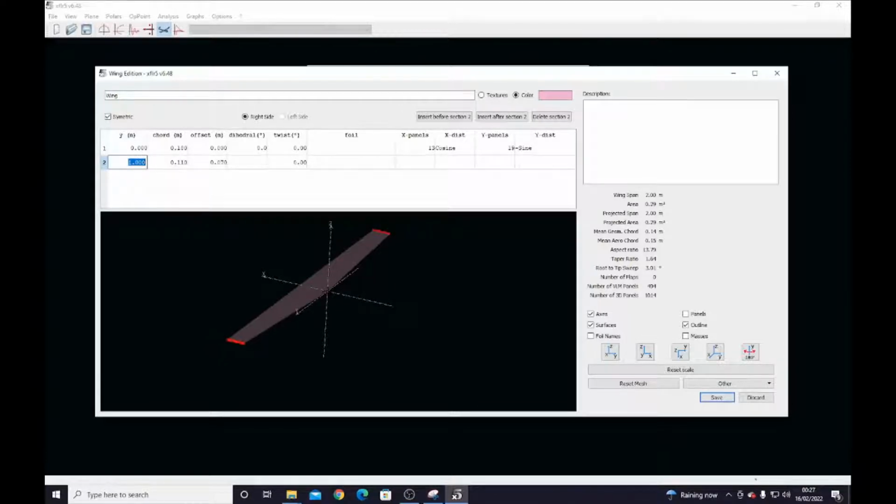It's a symmetrical wing, so you do one wing section and then it's repeated on the other side. So this is your outer section, this is your outer airfoil. If I change this to say 1.5, we've made it an extra 0.5 meters greater on this side. So your total wingspan is actually 3 meters because it would have been 1 meter each way. So that's 2 meters plus an extra 0.5, which comes to 3 meters. And again, obviously, if you change it to 0.5, it halves from the original, which is 1 meter.